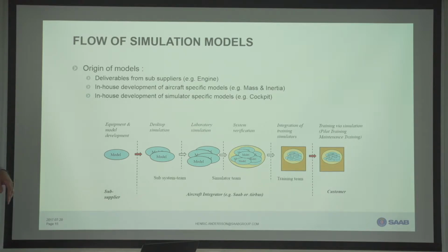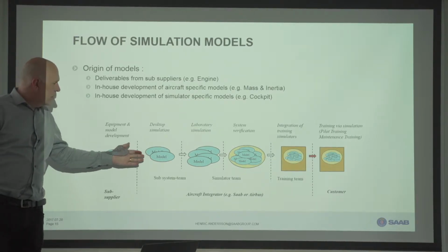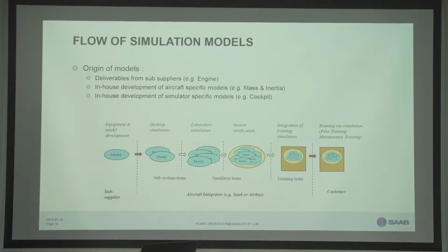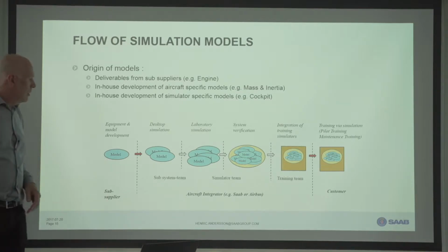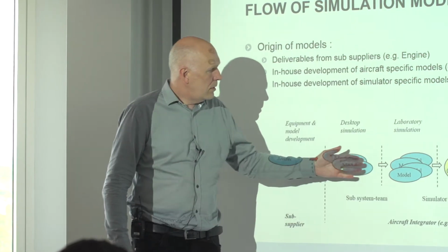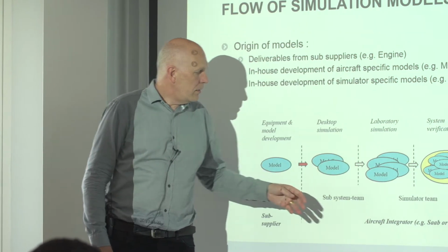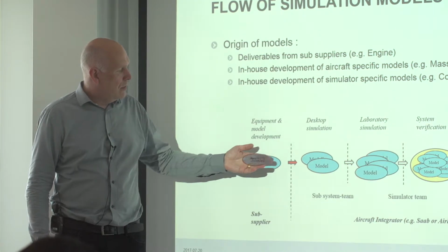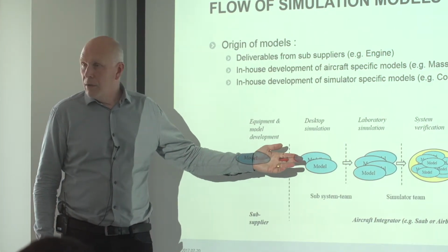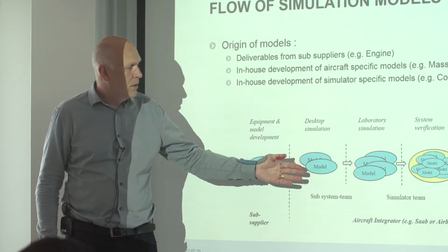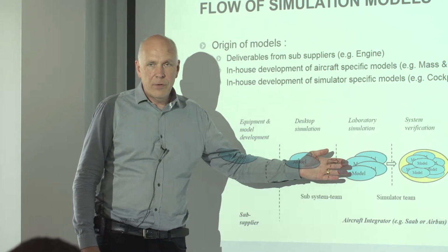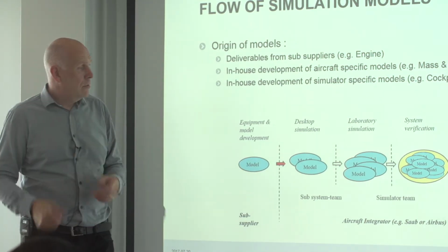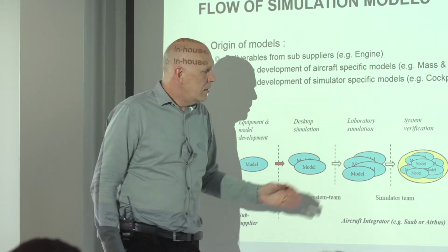framework, so to say. The models, we can integrate them pairwise or so on and do desktop simulation, typically in a tool like Simulink or pure code. And then we integrate more of them. So say that this could be the engine model. We connect that together with the FADEC, with a control of the engine, and then we can connect them, for example, to the fuel system to see the integration of the engine and the fuel system in some kind of laboratory.